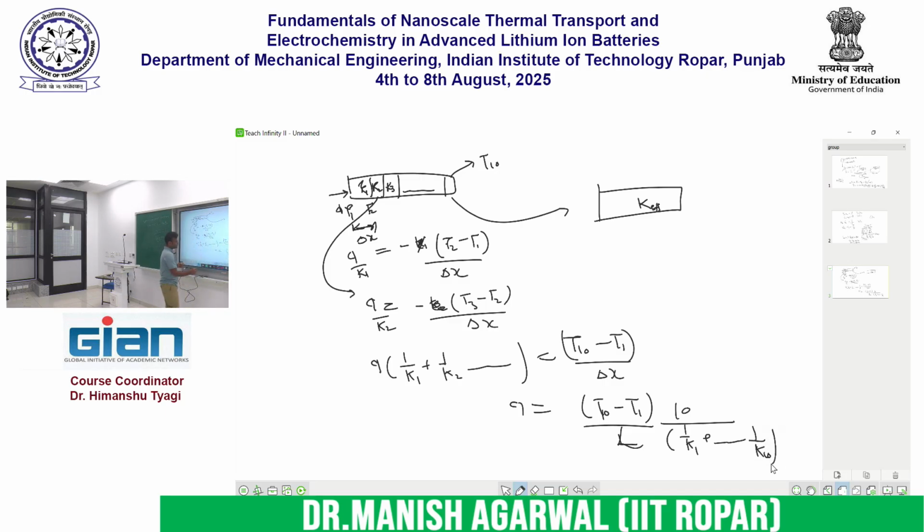So the effective conductivity is going to be 1 upon 0.1 upon K1 plus 0.1 upon K2, up to 0.1 upon K10, right? It is a very simple derivation and you can derive the effective conductivity. It is a very simple arrangement, that's why you are able to derive it. In case of a complicated arrangement, there are special computational techniques.